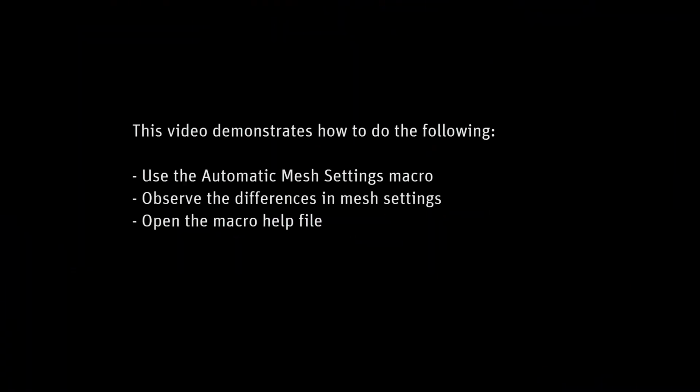In this video, you'll learn how to use the Automatic Mesh Settings macro in ANSYS Icepak to define global and per-object mesh settings for critical object types. This macro can be used by both new and advanced Icepak users to quickly create reasonable first-cut mesh settings.